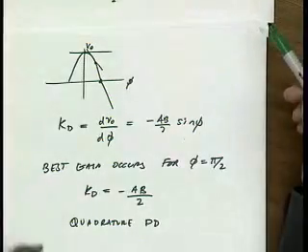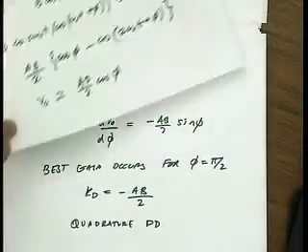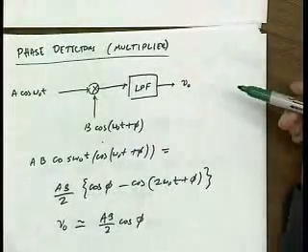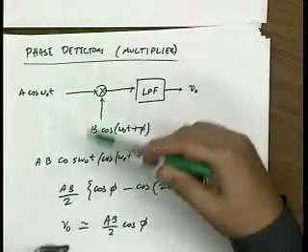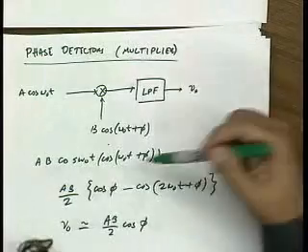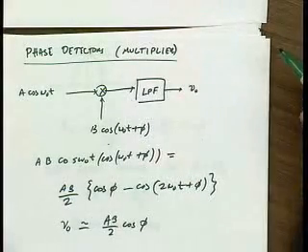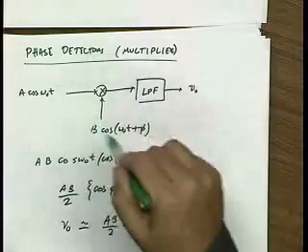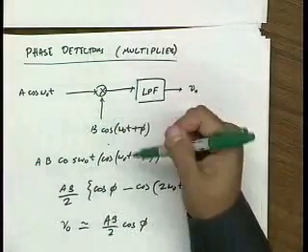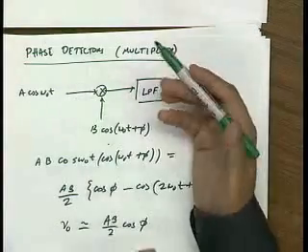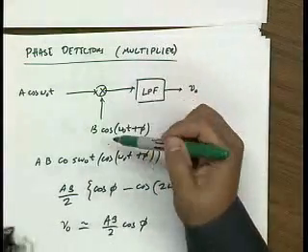Well, I'll say that this style of phase detection is really only used at really high frequencies. If you're locking to an optical source or you're building a really high frequency loop, you might use a multiplier. Because these two frequencies are actually quite low relative to today's technology, right? The reference frequencies are on the order of megahertz, tens of megahertz.